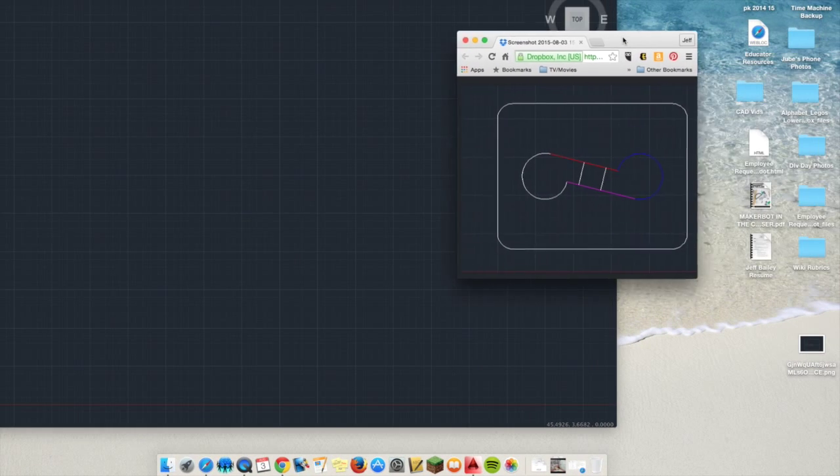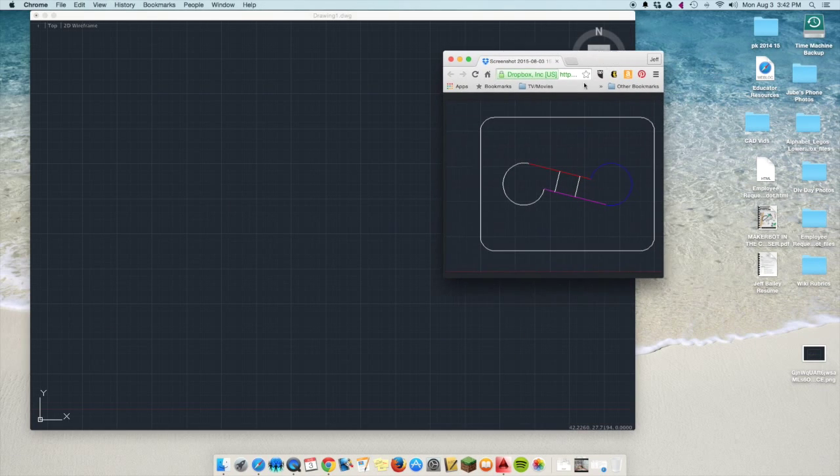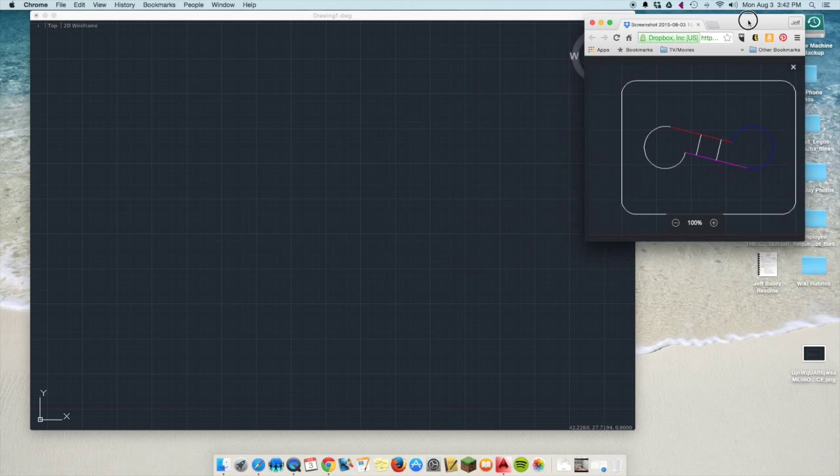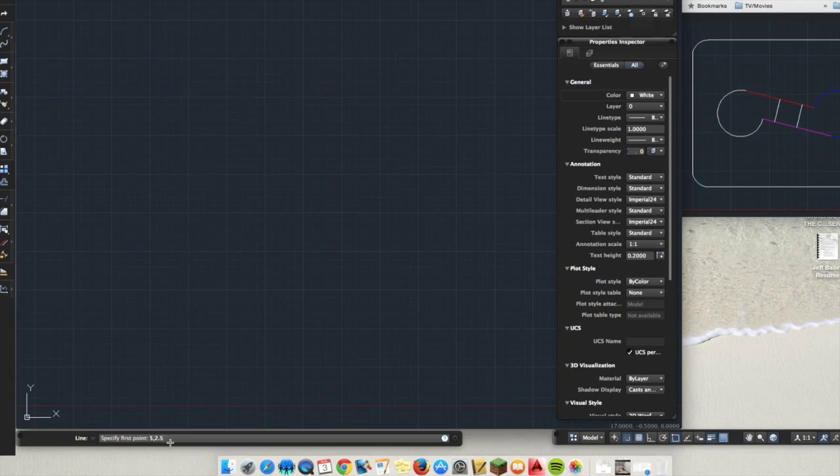Now, to get started with making this whirligig, we are going to make the outer box, okay? And to do that, I am going to do some coordinates with you with lines. So what we're going to do is make these 4 lines, and then we're going to use the arc tool that I'm going to show you to connect the edges so they're rounded like this. So turn on your line tool. Make sure you're in your drafting tool set. Turn on your line tool, and the first point for your line is going to be 5, 2.5. Let me go down here so you can see that.